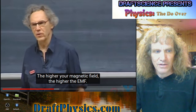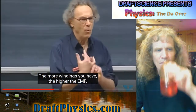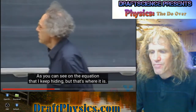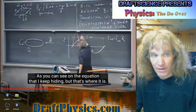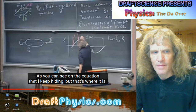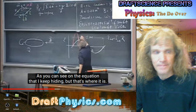So nothing can change. The faster you rotate, the higher the EMF. The more windings you have, the higher the EMF. And the larger the area of your loops, the higher the EMF, as you can see in the equation. But again, it's not the area that matters, it's the length of the wire, and they're just using area as a placeholder for the proportional variable, which is the length of the wire.